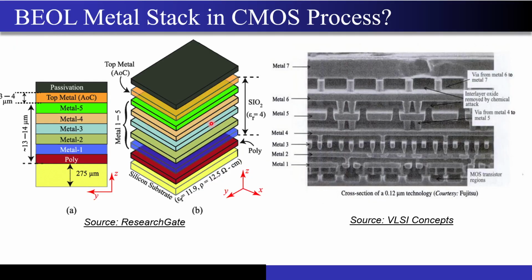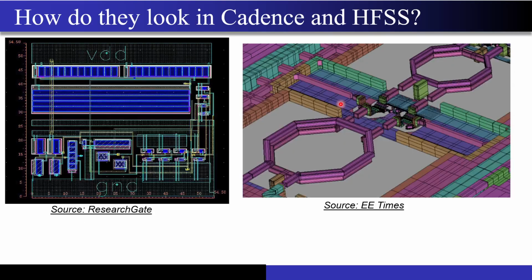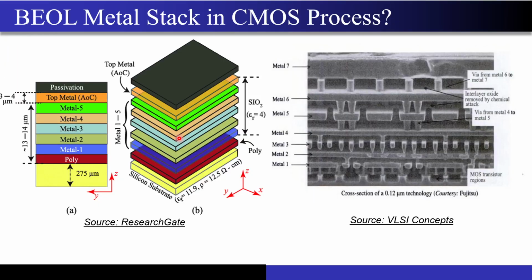So now this is how it looks over here, but when you design it in Cadence, this is how it will look in the layout. So these lines that you're seeing over here, the green color, the yellow color, probably these are the metal 1 and metal 2 layer lines which have been shown over here, correct? As you go up, the metal layer number actually increases. So this is what I was talking about, metal 1 and the metal 2 line, correct?